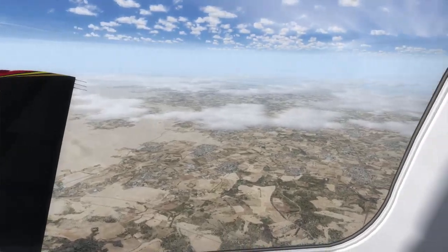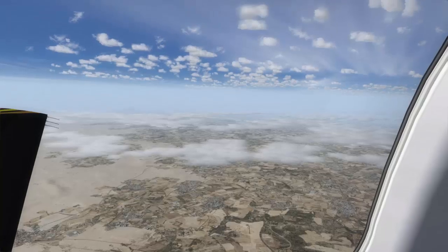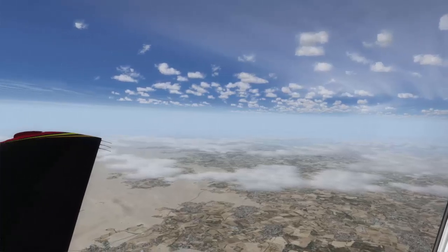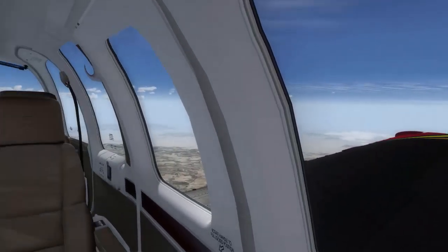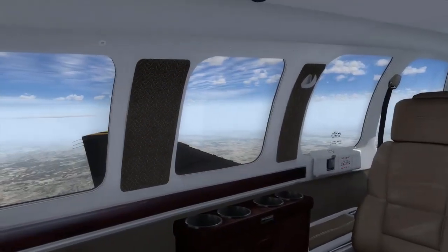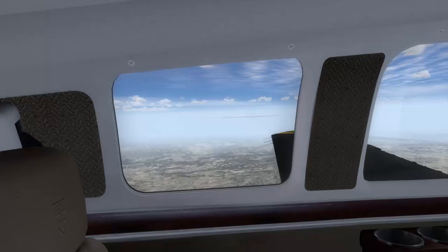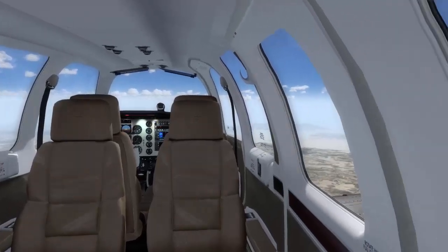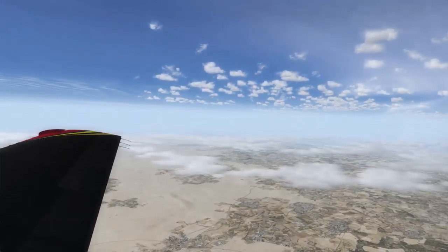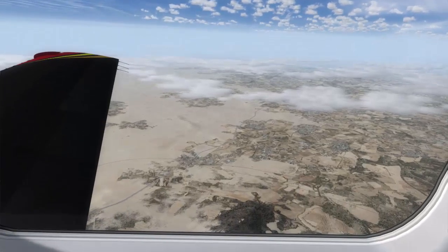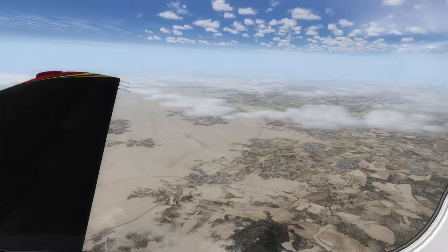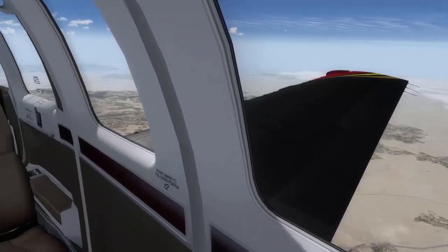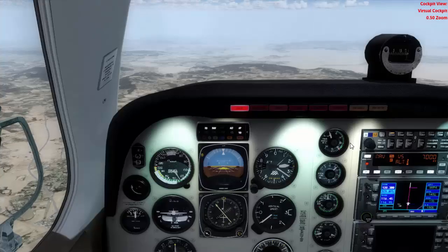So pay attention to that warning, but don't worry, because we don't need the gear up yet. And I don't know if you remember the indication of the manifold pressure, but we need to reduce a lot of power, because the aircraft is flying with its own weight. Have in mind this weight, and it is descending, so its own weight is pushing the aircraft to the ground. So we don't need to apply more power, and when we cut the power, it's completely normal. We don't have any value in the manifold pressure instrument. Even when descending, if it is not in the comfortable zone, the green arc of the manifold pressure gauge, we won't have any problem at all.